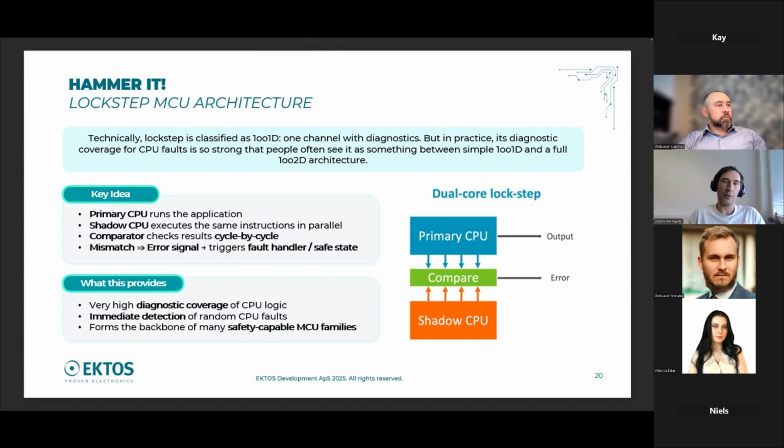One example of a safety capable component is a lockstep MCU. This MCU contains two similar cores, which are rotated 90 degrees physically on the crystal.